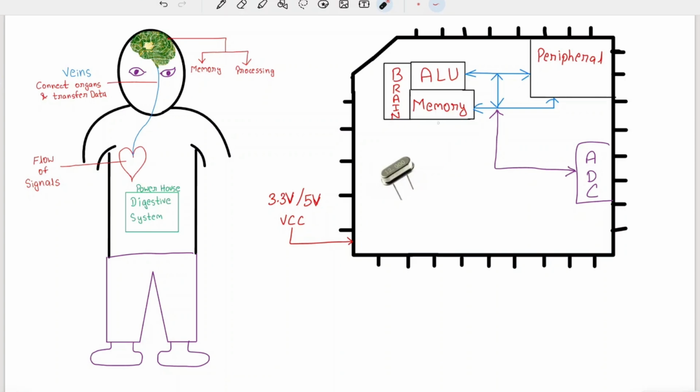To display the data, if we use a normal LCD screen that can be operated using GPIO, then we need to attach the GPIO peripheral as well. Now, because of the ADC peripheral, we can read the voltage data and process it with the brain and display it on the LCD display via the GPIO peripheral.